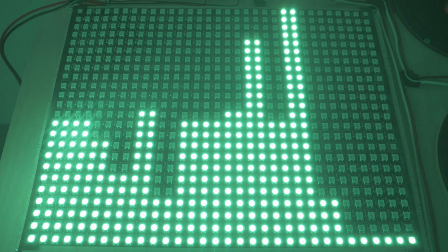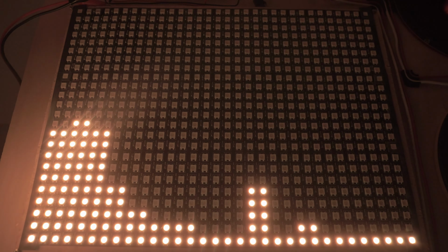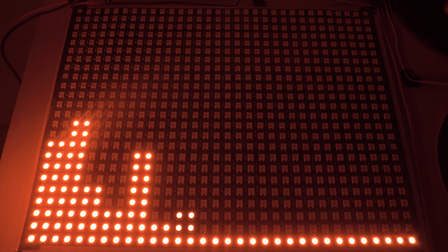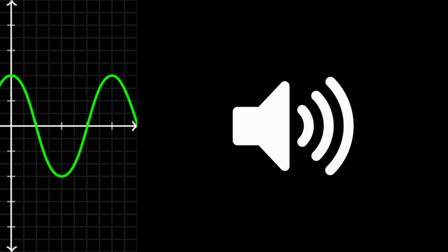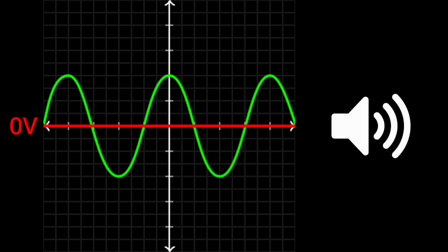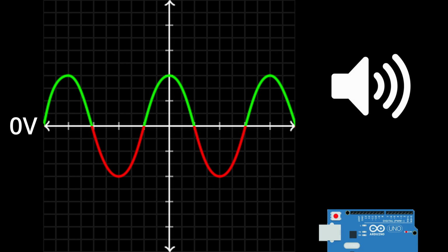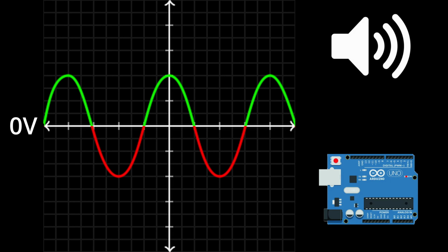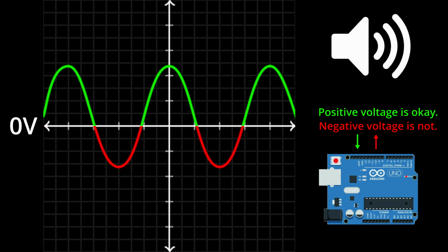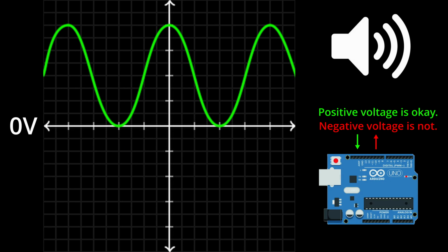Before doing that though, I want to move on to making the spectrum analyzer that will light up with the music. The most important thing that I explained in my last video that I'll quickly summarize is that the analog audio going to the speakers is centered around 0 volts, meaning half of the audio signal is negative. When connecting to one of the pins of the microcontroller that will read the audio levels, you don't want the voltage applied to those pins to ever go negative, because pulling current from the pins while you're trying to read from them will damage them over time. So, we need to bias the voltage up enough that it never dips negative.